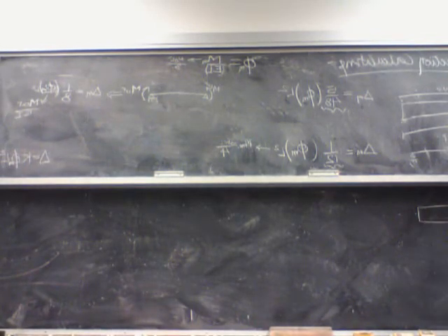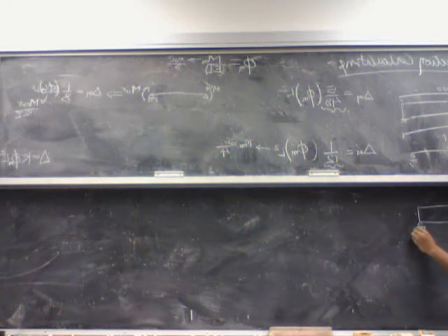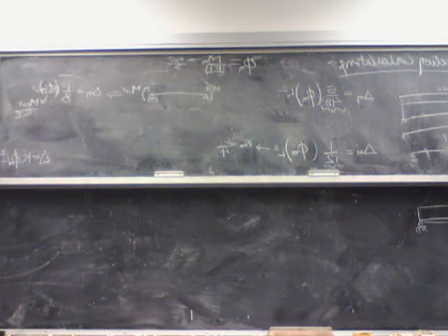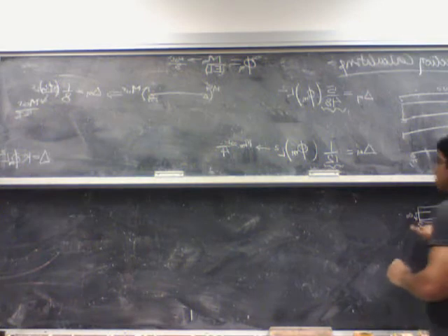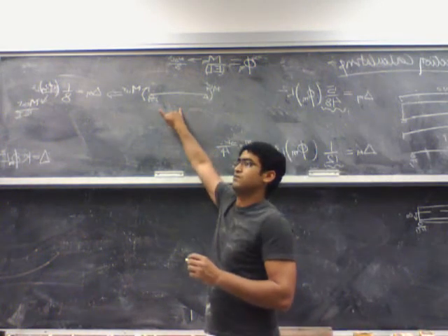Now let's say I have a beam which has a constant eccentricity tendon on it, with a constant eccentricity of, let's say, E naught. What is the moment diagram for this case? What is the moment due to a pre-stressing strand with a certain eccentricity? It's minus F E naught, right? So if my E naught is constant, that means my F E naught is constant. That means this case is very similar to the last case.